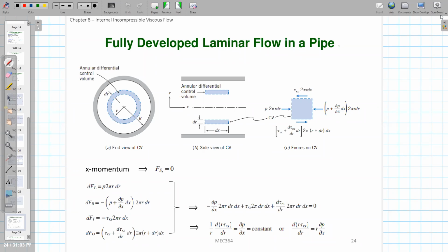If one plate is moving, it is not necessary to give an external pressure drop to force the flow to move, because the top plate is already moving, and because of the viscous force, it will create a shear layer and drag the flow behind it to move.